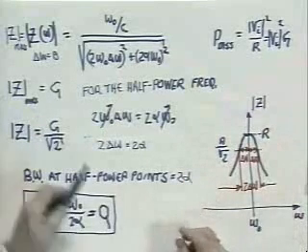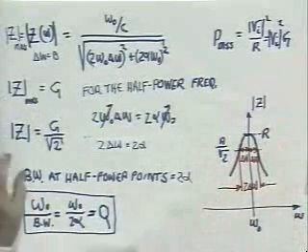So we've seen Q. It arose first in the time behavior of this circuit, where we noticed that Q is defined as a measure of the energy loss, a reciprocal of the energy loss per radian divided by the total stored energy. To put that in non-reciprocal terms, the total stored energy at any point in time divided by the energy loss per radian is Q, omega naught over 2 alpha.